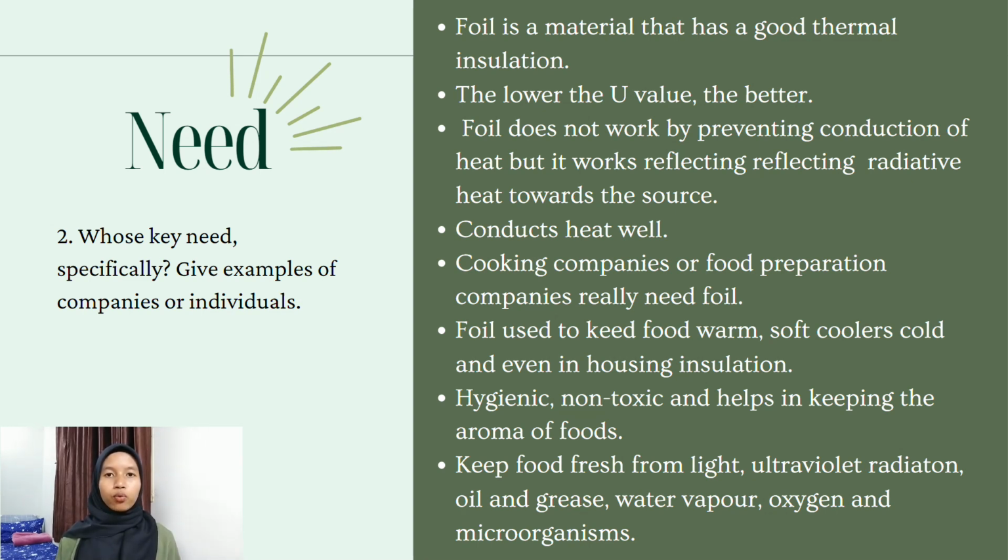To explain why, we have to know that the lower the U value, the better. But foil is different, because foil does not work by preventing the conduction of heat, but by reflecting radiative heat back towards the source. It is a great reflector of thermal heat, although it also conducts heat well. Companies like cooking companies or food preparation companies really need foil because it fulfills every need.